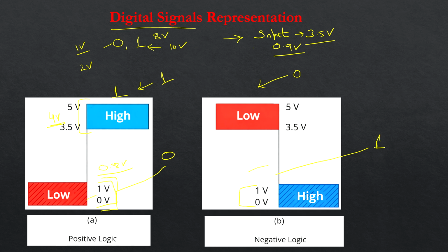So this is how we decide what is 0 and what is 1. So you cannot directly say it is a voltage, it is basically a range of voltage, and here is a no man's land, where we are assuming that we are not getting voltages from 1.1 volt to approximately 3.4 volt. We are not getting those voltages. Okay, thank you.